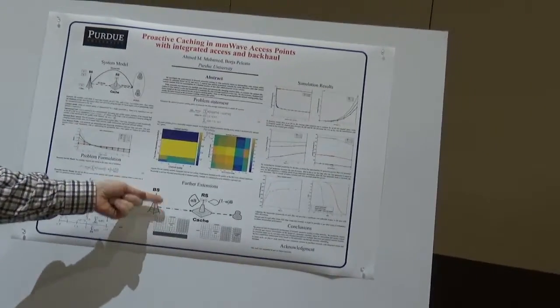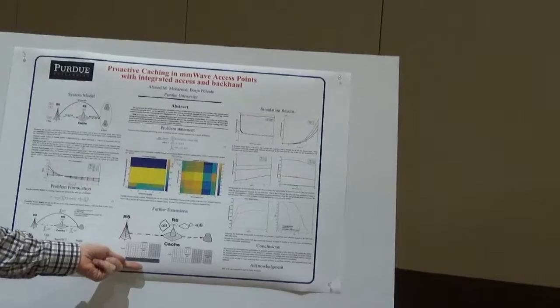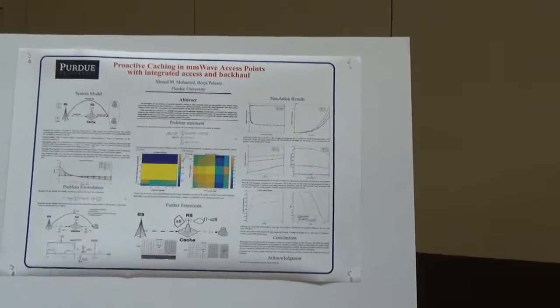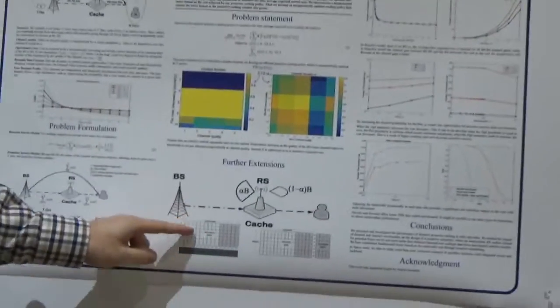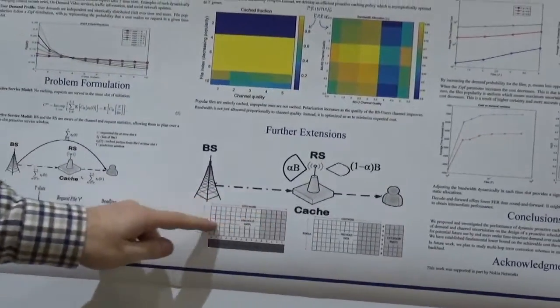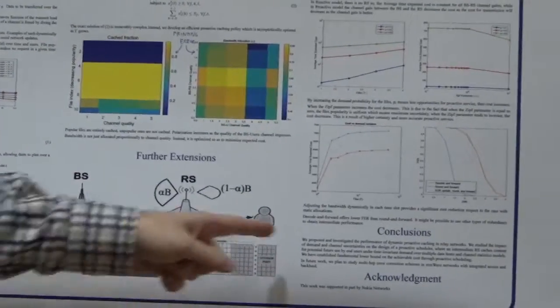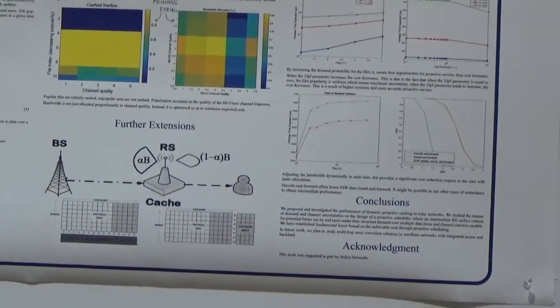So using an erasure code across different code words at this level, the relay station will be able to decode this erasure code across the code words so as to improve its estimation of these bits. Then it can basically re-encode those bits, which are hopefully better, and forward them to the users. So that's basically my two cents.